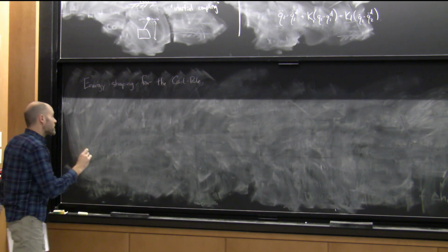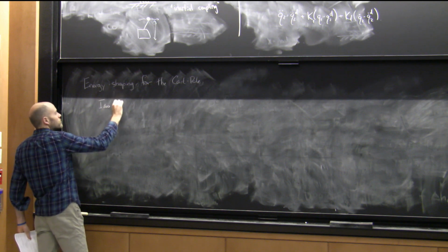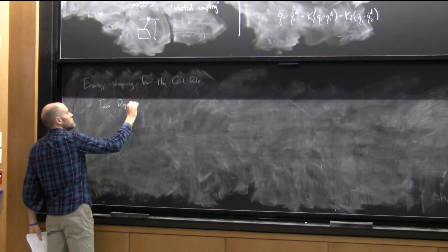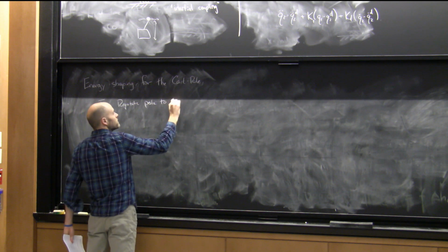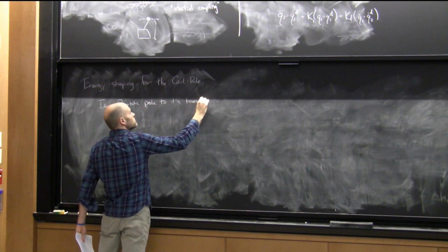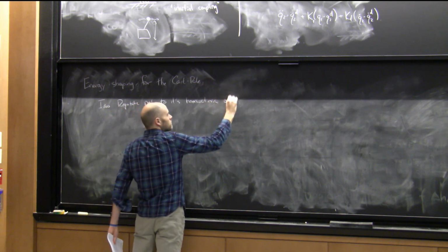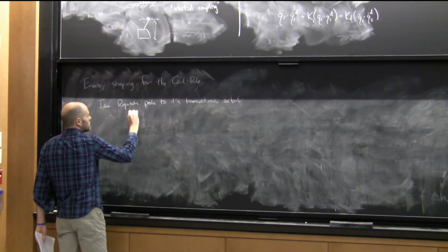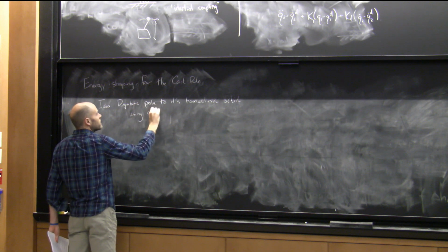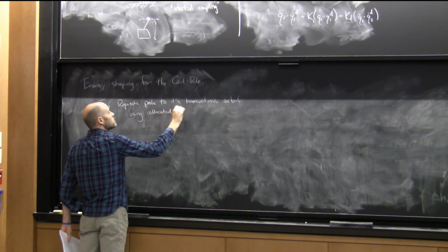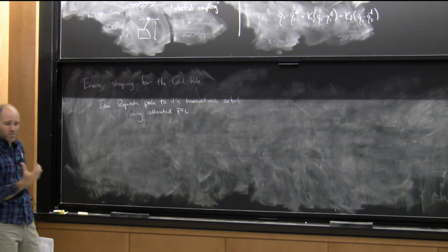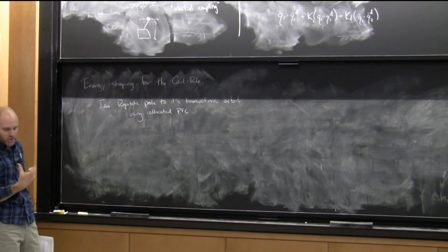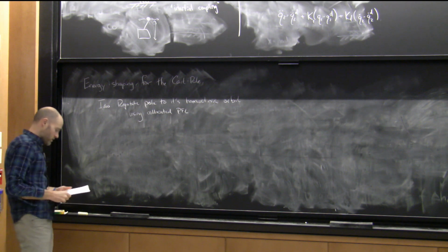So the idea is, let's regulate the pendulum, the pole, to its homoclinic orbit using co-located PFL. Because if I've done that, then I'm already controlling the cart pretty well. While I'm controlling the cart pretty well, if I can get the pole up, then it's a pretty simple thing to add a little bit more work to stabilize the cart.